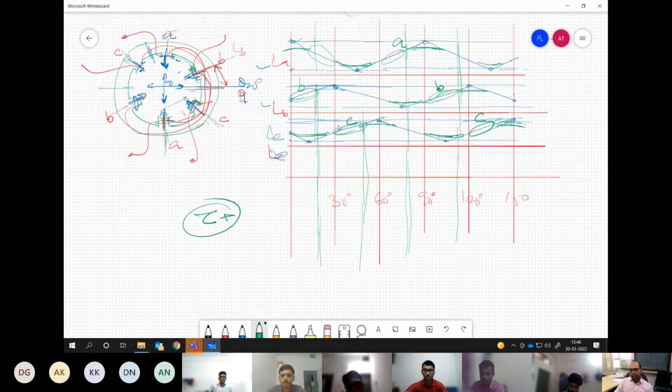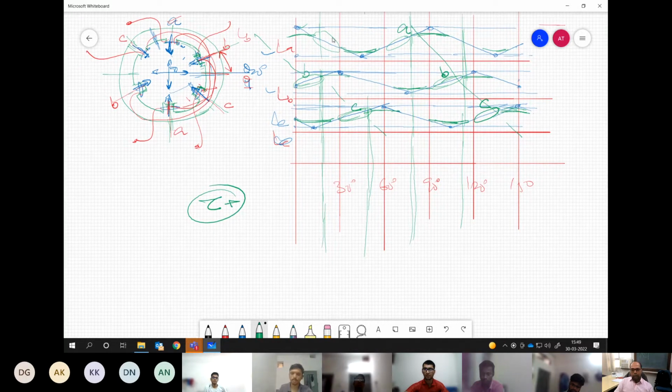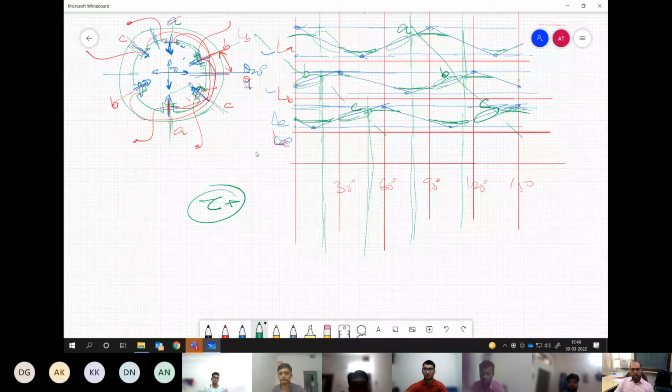If you do for the negative torque, again you will see that it's going in the reverse sequence. Understanding my point? Now it is coming A, B, C, then A, B, C, and so on it's going. So what we need, basically we need to know these positions for which these particular coils A, B, and C would be excited. That's what I was trying to tell. So now we know where our ∂L/∂θ for a particular phase is going to be positive.